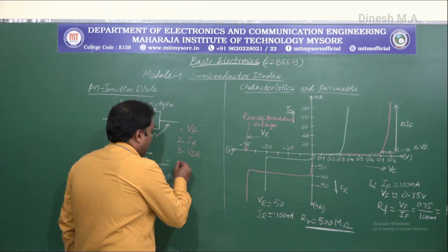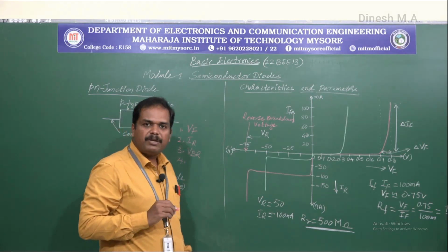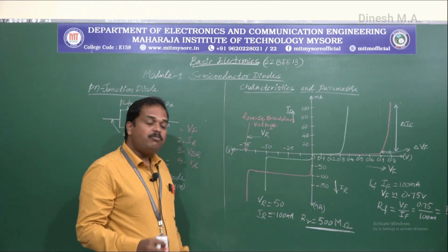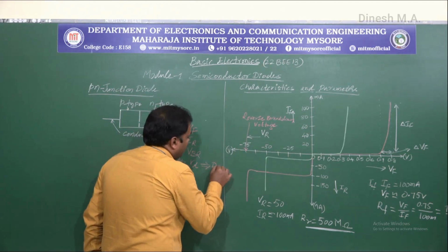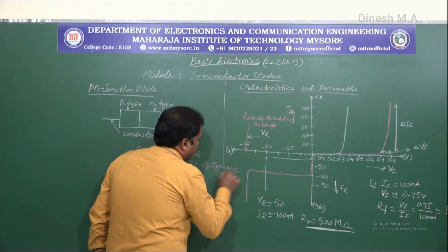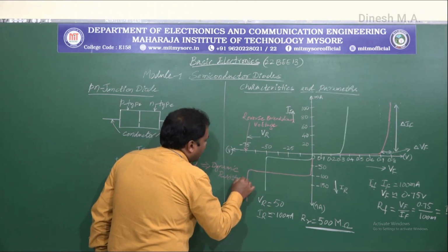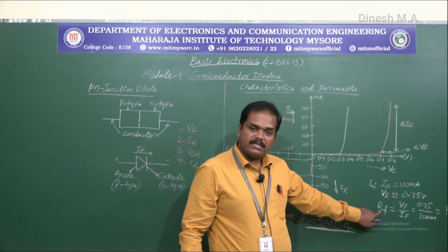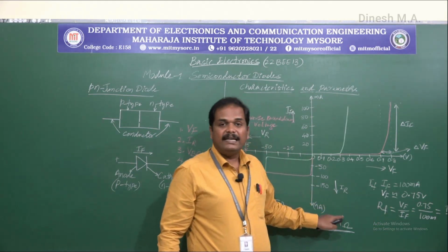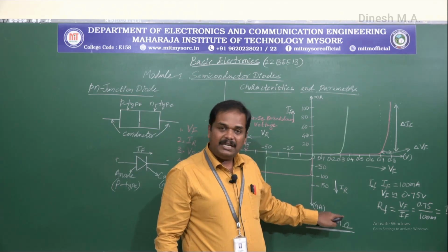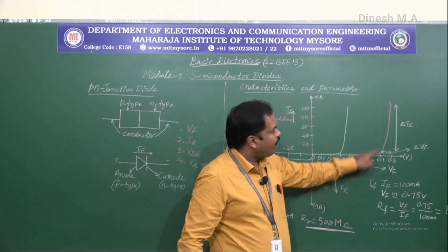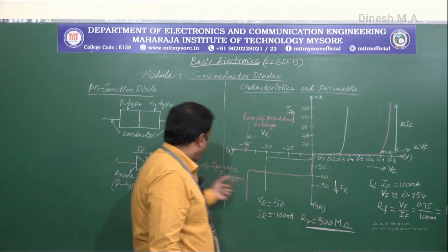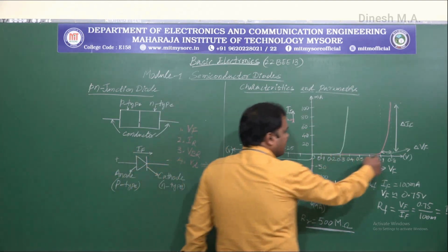The VBR. And the fourth parameter with respect to any diode is RD. RD is dynamic resistance. Now, just now we calculated the resistance in the reverse bias condition and in the forward bias condition. So these are the static resistance or the DC resistance. For given VF and IF values, we found out the resistance here. But now RD is the dynamic resistance in this given range.